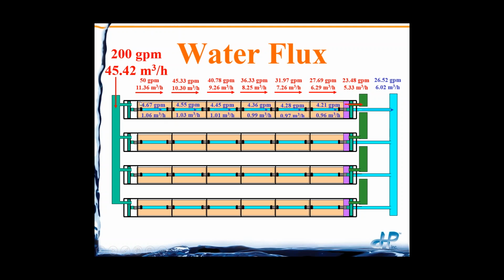So in the pressure vessel, the GFD is highest in the first inch or centimeter and lowest in the last inch or centimeter. Well, water flux, again, permeate flow per given area of membrane per given amount of time, is the main controller of your fouling rate. Since GFD is the highest here, then it means that that's going to be your highest fouling rate.